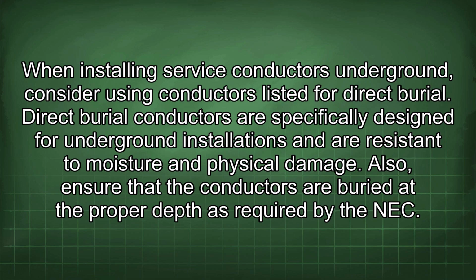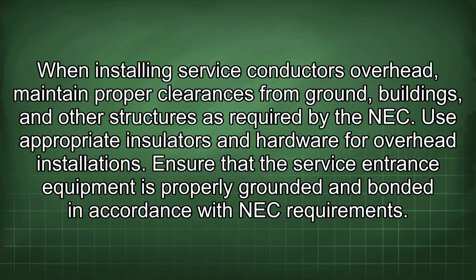When installing service conductors underground, consider using conductors listed for direct burial. Direct burial conductors are specifically designed for underground installations and are resistant to moisture and physical damage. Also, ensure that the conductors are buried at the proper depth as required by the NEC. When installing service conductors overhead, maintain proper clearances from ground, buildings, and other structures as required by the NEC. Use appropriate insulators and hardware for overhead installations.